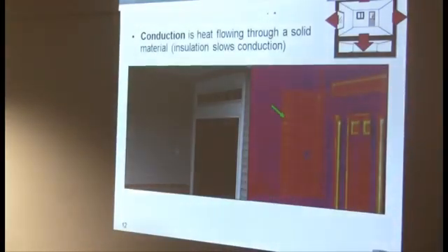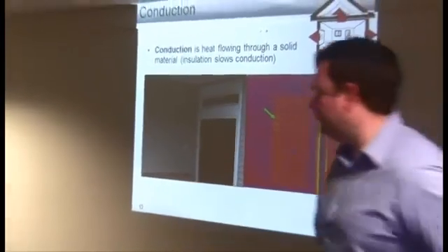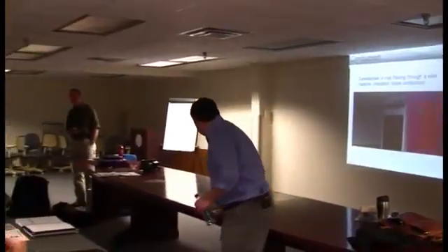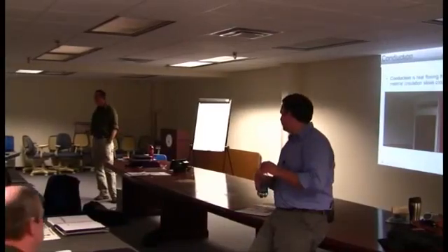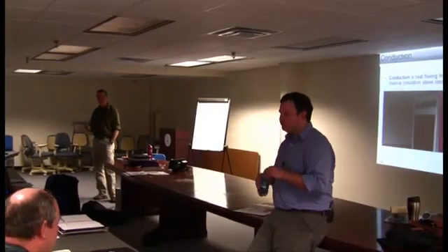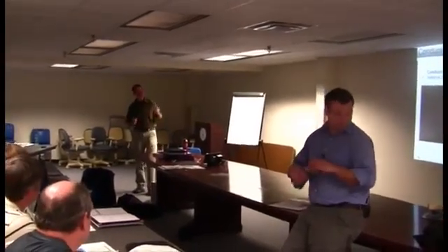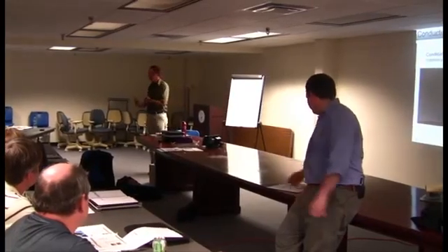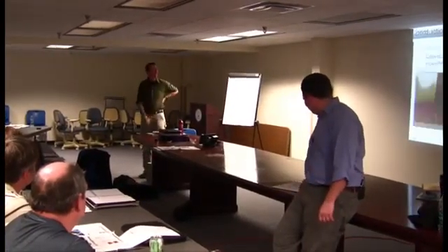an insulation inspection is so important, to catch it before drywall, to actually go and see: did they insulate behind the tub? Because the tub, of course, often gets set before insulation shows up. So it needs to be done, and conscientious builders are paying attention to it. But you have to, what is it? You have to inspect to get what you expect. I think that's what they say, or something like that.